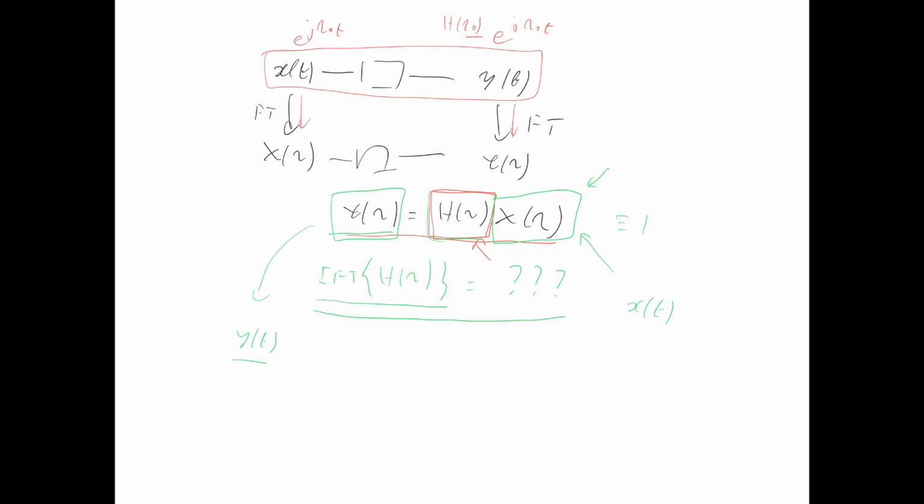While there are some mathematical intricacies which I am ignoring, if we just go to a table of Fourier transform, inverse Fourier transform pairs, we can find out exactly what we need x of t to be if we want its Fourier transform to be 1. Looking up in tables, we see that we need x of t to be the Dirac impulse. And this is the proof in the other direction that the Fourier transform of the impulse response of the channel is H of omega. Just a reminder of what the Fourier transform is mathematically.